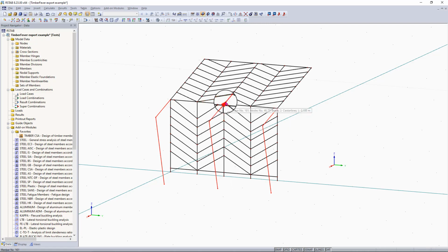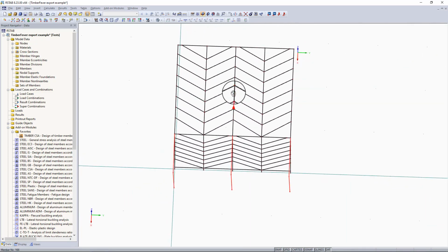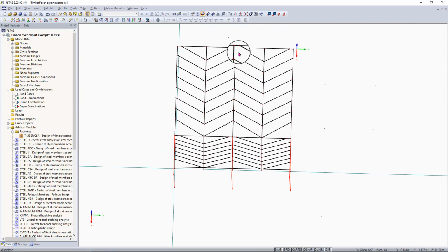And I also want to highlight all of our whole beam member here, which you can see is in separate lines. So what we can do is rotate this model, and then we can just simply drag from left to right and select all these individual lines here. Don't worry if you select lines that you don't want to select, you can always deselect them after doing this.